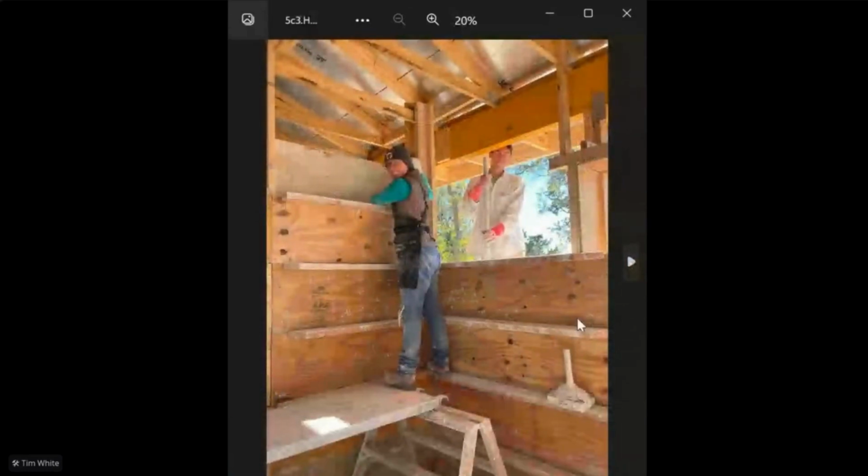This is a good photo in the corner. You can see Danny here. She's standing on top of that little ledger board that we use to lock our forms in and together. It gives a little footstep, ease of accessibility sometimes. Underneath her foot, you'll see that they're cut at like a 30-degree angle off of the corner, so they're actually supporting all the way into the corner there. And you can see how we've attached it over on this side to that rough 2x that's added into our formwork that will literally come out, but we use it as an anchor for our slip form as we're going.